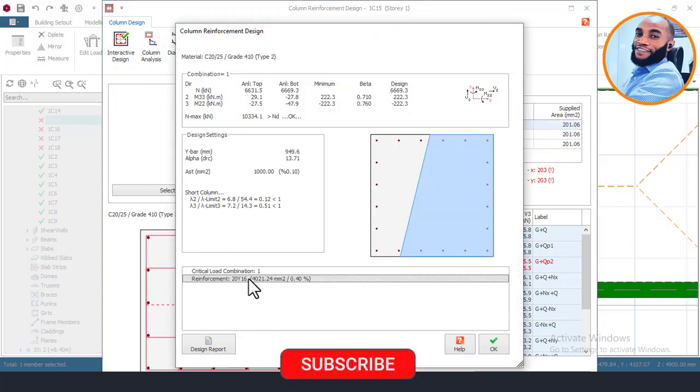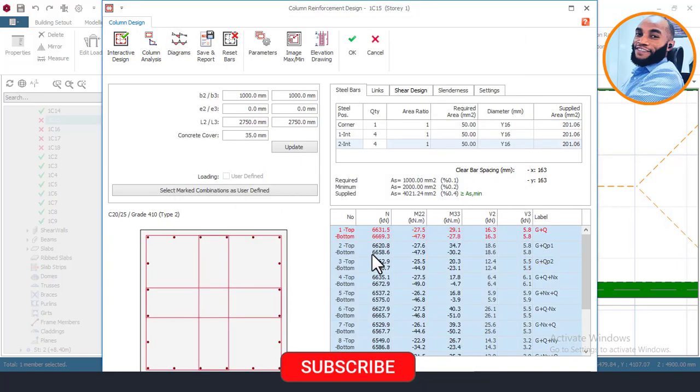You can see that 20 number of Y16. But our advice for this 16, this is a 16 story building, and I would like to use Y16 for my column because of the high-rise building and all that. So our advice, don't go and increase your column section very much just because you want to have a lesser bar.